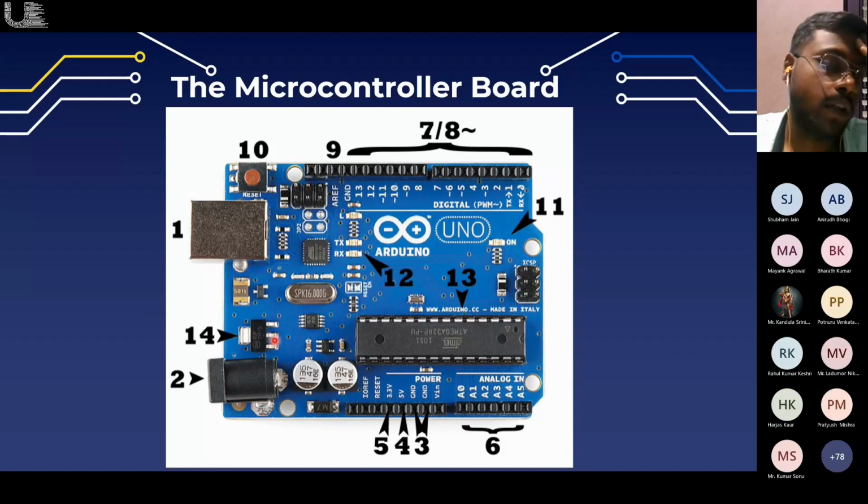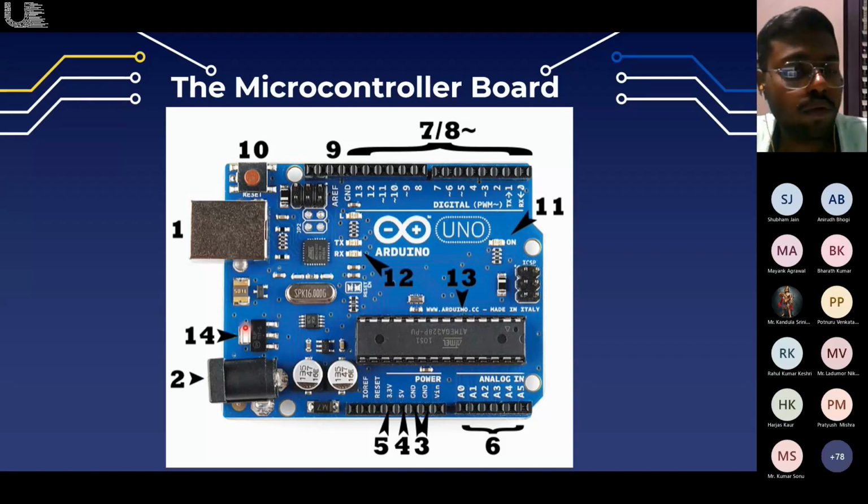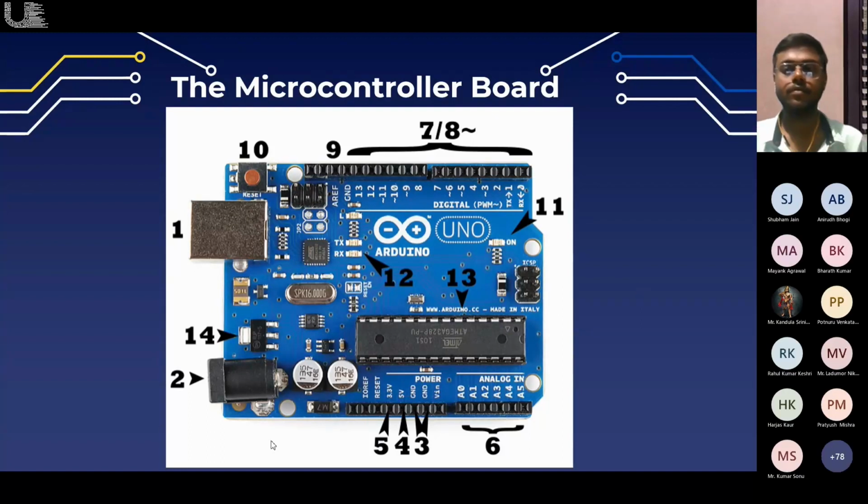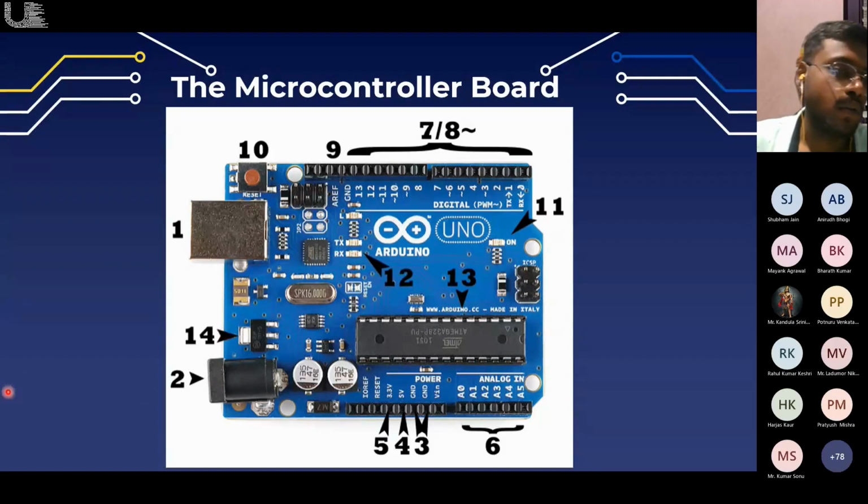This is the voltage regulator. We do not need to engage with this, but it regulates the input voltage if it is not within the specified range, to prevent the board from being damaged. The upper limit for the Arduino board is, I think, 20 volts. Anything greater than 20 volts plugged into the Arduino board will of course damage the complete board.